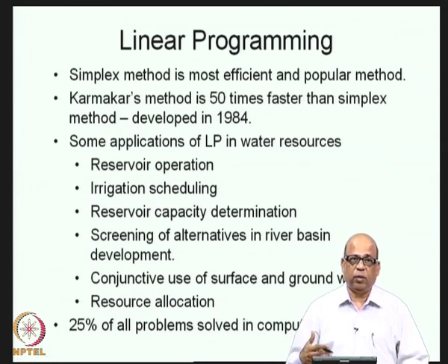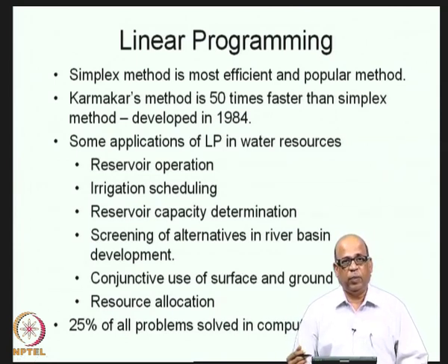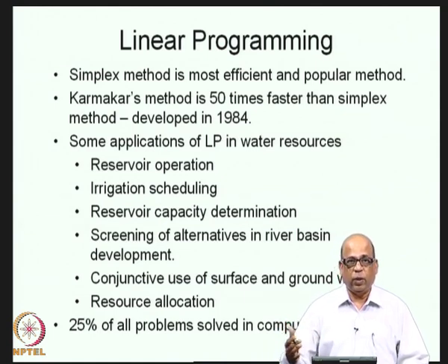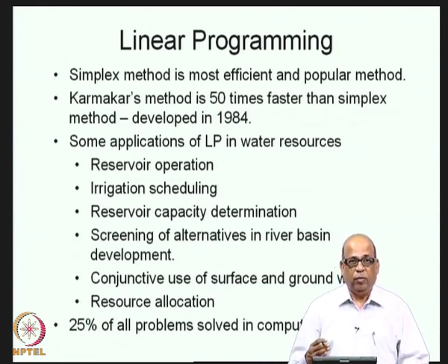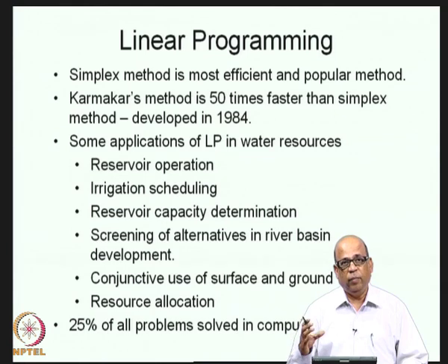Look at systems of Narmada river basin where you have 14 or 15 major reservoirs which have to be operated in an integrated way. So, you are looking at optimization of reservoir operation of large systems. Even when you are talking about a single reservoir optimization, you have multiple functions: water supply, irrigation, flood control, hydropower, downstream water control and so on. So, you have a single reservoir